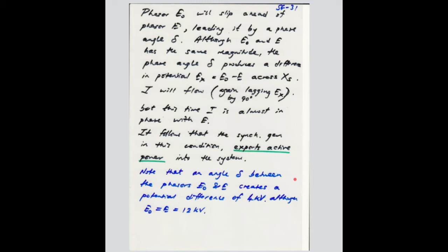So in the last section we looked at how active power can be transmitted from the machine to the utility by applying more steam on the turbine, or a higher flow rate of water on a hydro turbine. That will shift the phasor of E0 at a certain angle with respect to the terminal voltage, right?